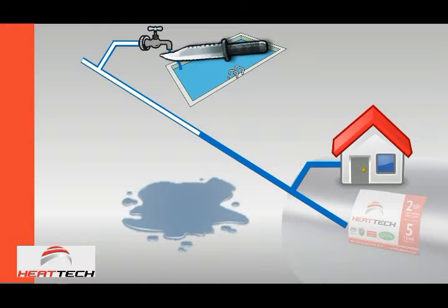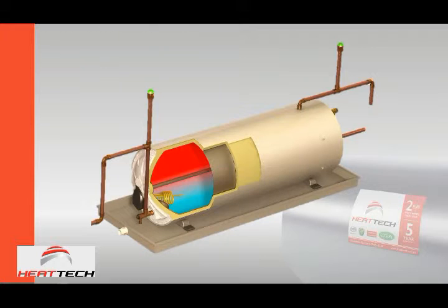And this is exactly the principle that the vacuum breaker uses. It uses the principle of allowing air in at the right conditions. In other words, when air shouldn't be in the line, it won't be in the line. The plumbing system will be sealed. But when the conditions are right, when conditions try to force water to run in the wrong direction, for instance, and could potentially cause contamination, it would rather allow air into the line, preventing any siphonage or any movement in the wrong direction. And in that way, keep the line safe. So as soon as the pressure comes back, it fills the air gap, and you have clean, fresh water again.